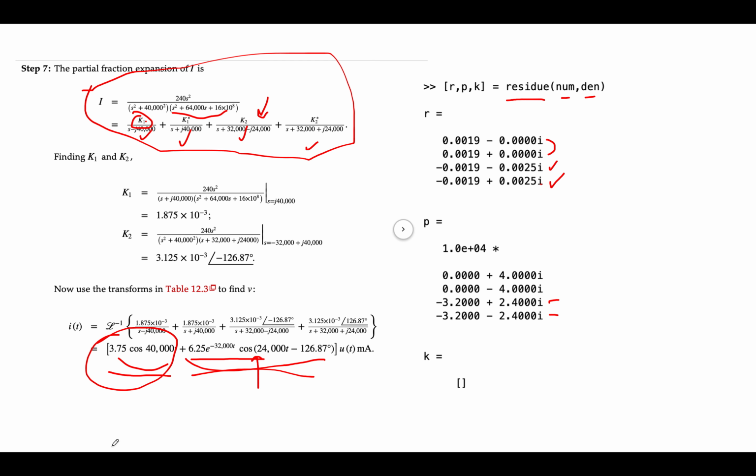So I thought this was an interesting problem, and I thought it was worth going through because it does show where, even with a sinusoidal source, there are some transient effects. Now, oftentimes in a 60 hertz circuit, so let's say that the frequency of our source was closer to 60 hertz, a lot of times what you'll find is that this decay rate is so rapid that it literally is buried in the first cycle of the cosine function. And so that is why in AC analysis we can use phasors and ignore the transient effects.